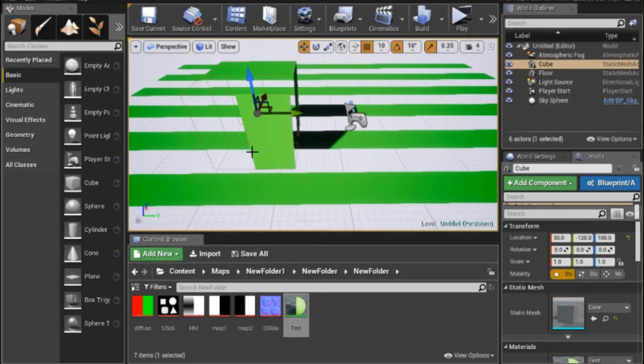For what can you use this? For quite different things. As example, for foliage, if you make a tree and you don't want to create every single leaf out of a mesh, you can use a picture or anything like that of a leaf with a black background and keep the leaf white, and then you can make every single leaf create a quite complex leaf form with a very simple mesh, because you just can use a plane if you want to.